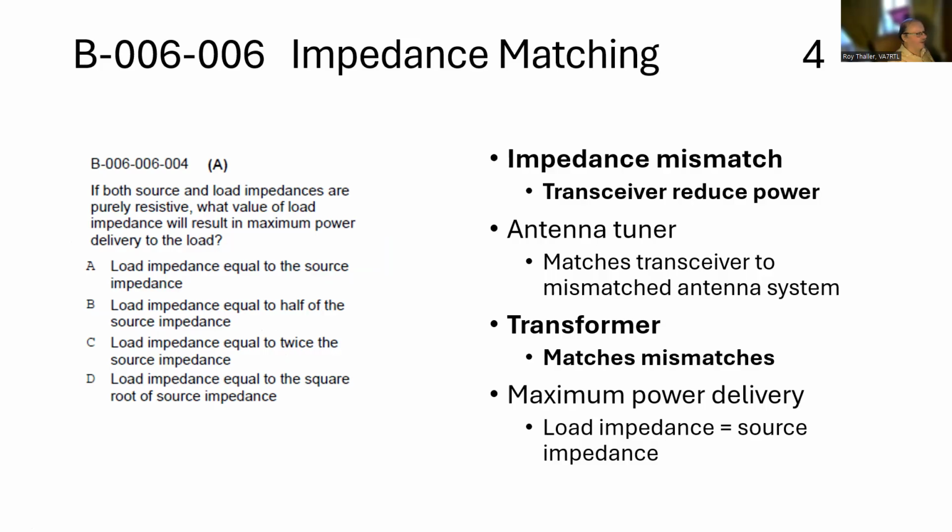If both source and load impedance are purely resistive, what value of load impedance will result in the maximum power delivery to the load? So this is when the load impedance is equal to the source impedance, you get maximum power transfer. So A is the correct answer.